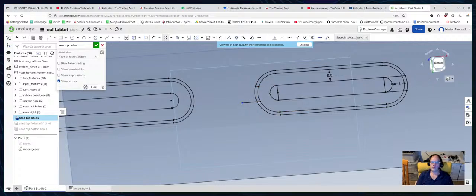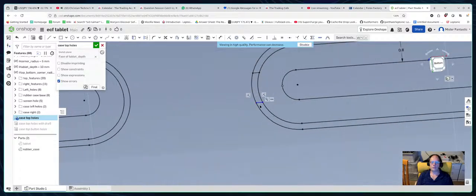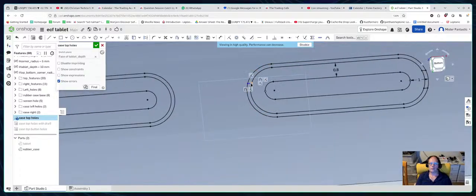trim, trim. We don't need that. We don't need that. We don't need these either, honestly. Okay, I can do that. I can't get rid of that. Take off trim mode. That thing needs to be horizontally constrained to that. H for horizontal. It didn't help. Okay, fine. Delete it.